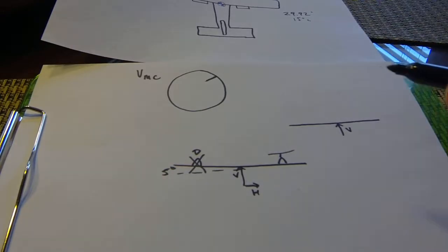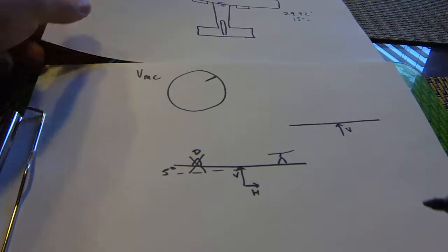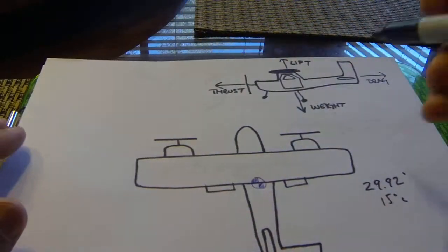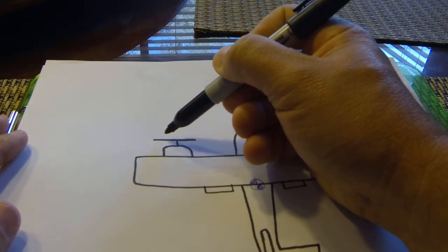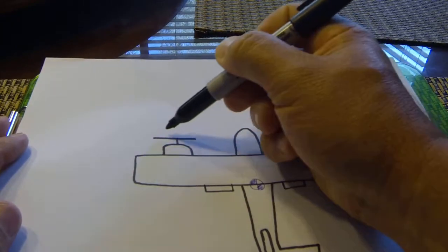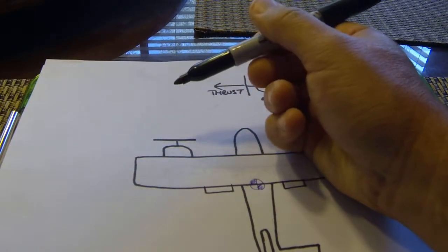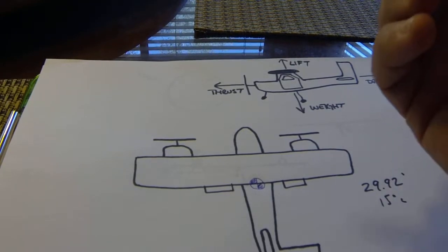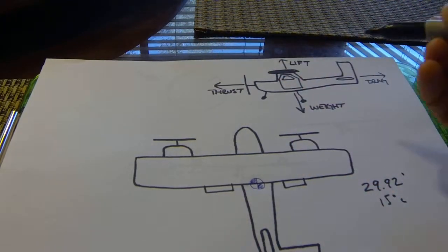So we're allowed up to 5 degrees into the operating engine. And finally, for VMC determination for book values, the inoperative engine needs to be windmilling. If it has auto feather capability, we're allowed to let it auto feather, but for most aircraft, it needs to be windmilling.